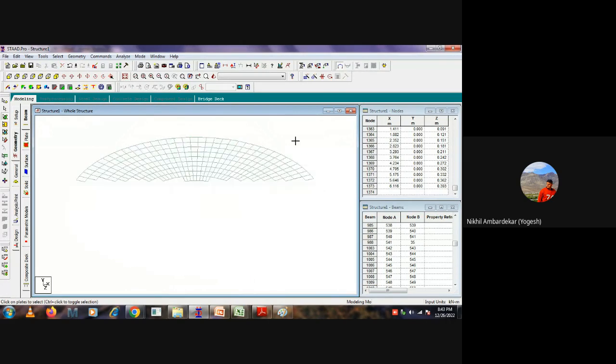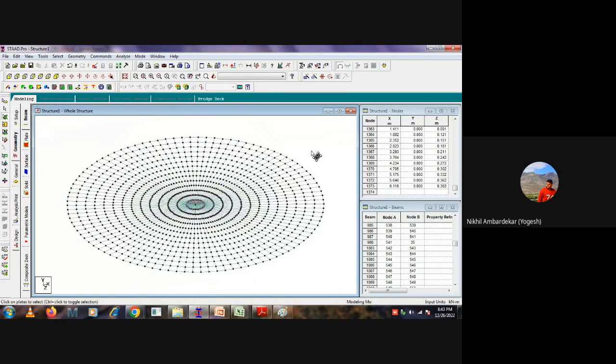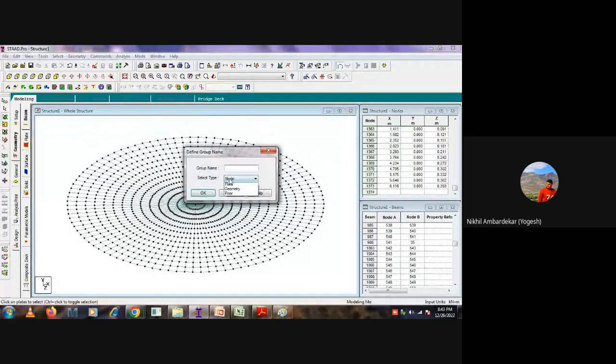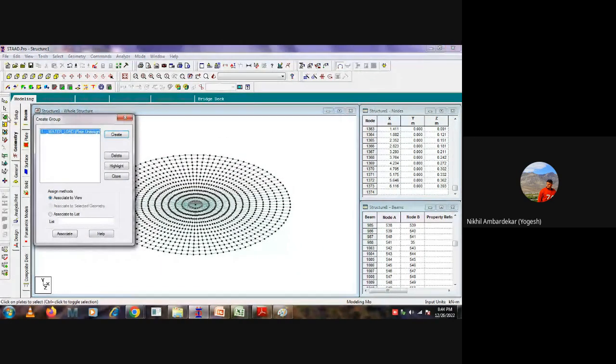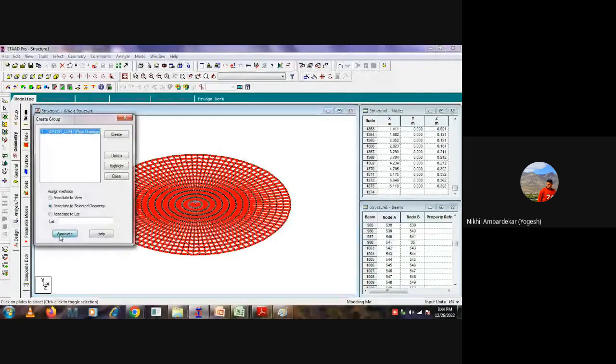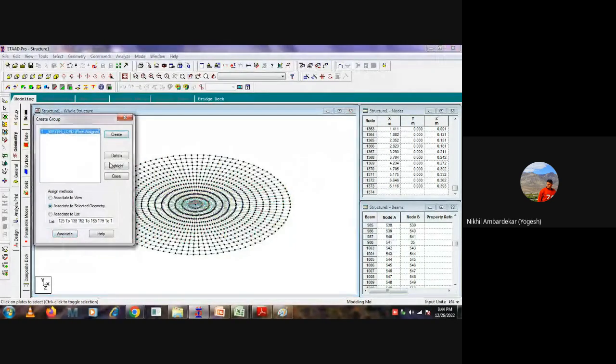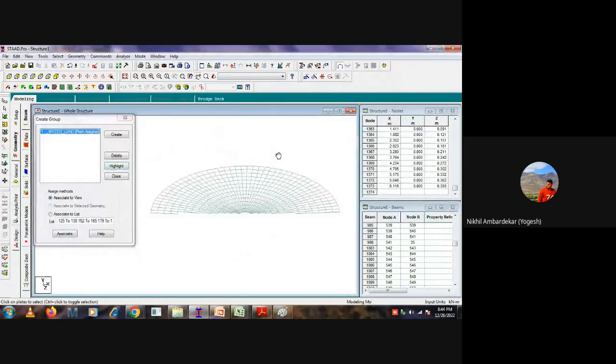So these are the plates. Just right now, create some groups. Plate, water, load. Because these are the plates which are subjected to the vertical pressure of the water load. Correct? Okay. Select all plates, and assign this. Just check whether it is added or not.